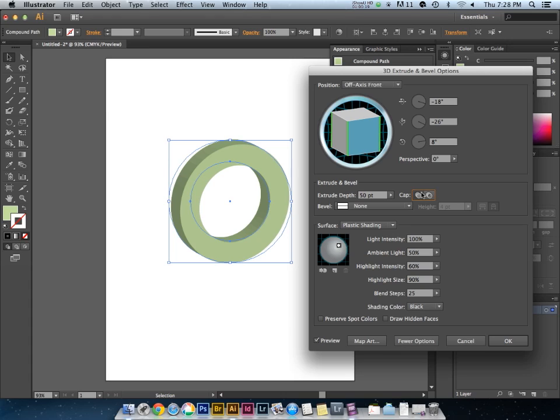And you notice there's two different caps that are available to me here. There's the solid appearance cap, which is the default. If you click on that, it actually fills your object completely solid. It's rendering like a solid object. The other one will not cap the objects.